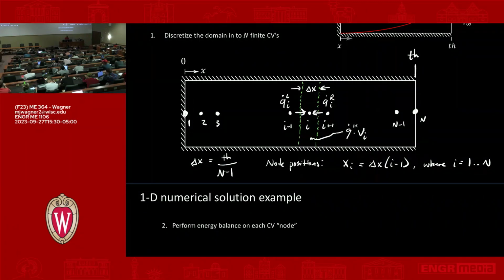So the control volume that we use has to cover the entire dimension for any other coordinate. Right, so Y. In this case, we have Y in this direction. We're saying there is no temperature gradient in Y. So I don't need to discretize in Y at all. So I can capture the entire effect of temperature changing by drawing a control volume that covers the entire Y span and is just discretized in X.